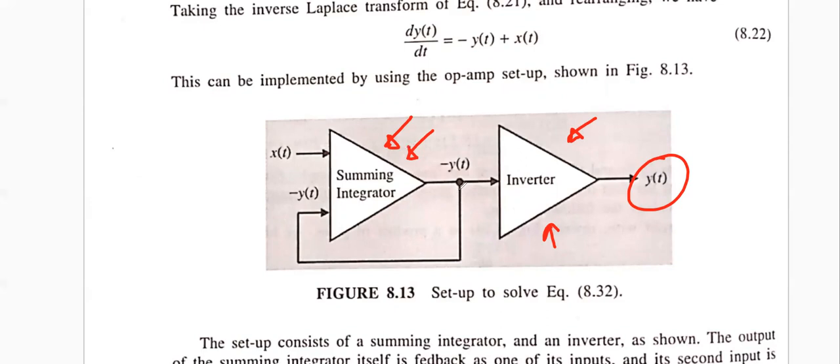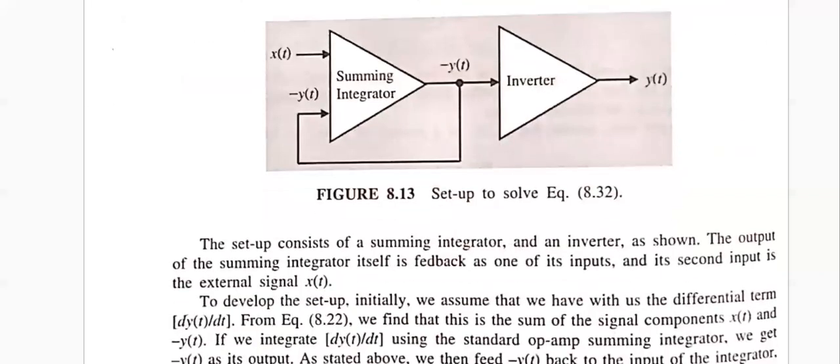And we have learned that we definitely need this feedback circuit for this kind of orientation. So that shows that for any kind of filter presented by an analog circuit, we always need the feedback. Without any feedback, you can't imagine any practical analog filter representation. That is why all of these have feedback, and that's why they are of the IIR type. There is no FIR type, finite impulse response filter. All the analog circuits have infinite duration impulse response filters.